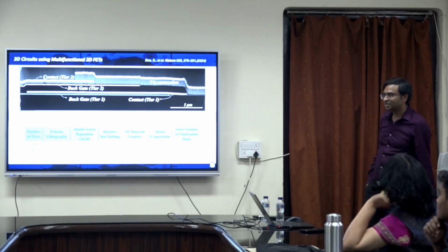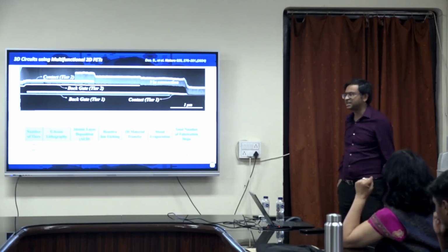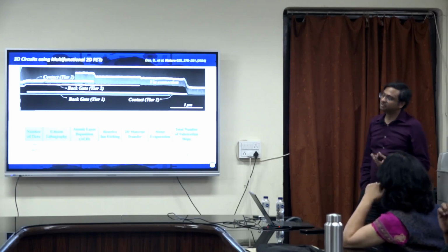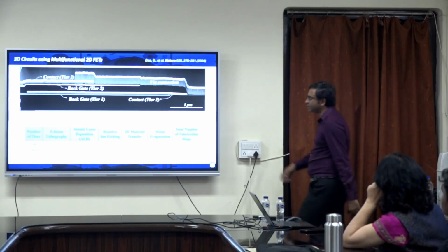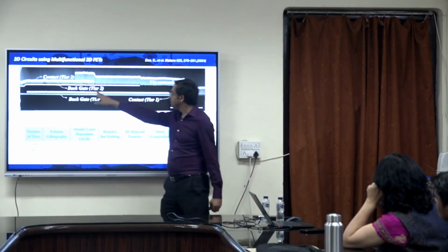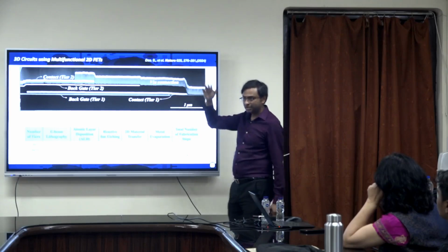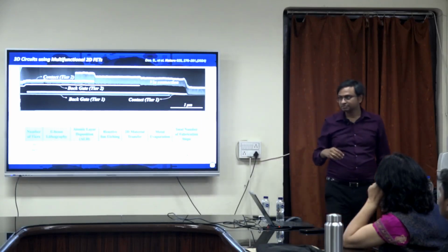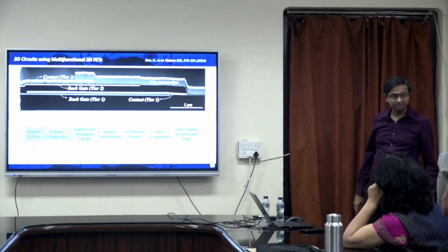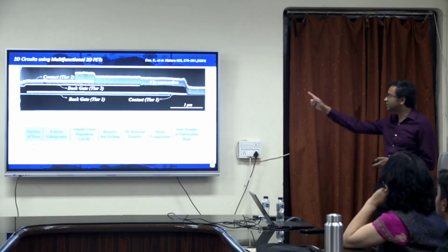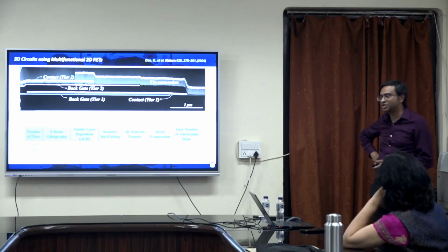Via connections over here I think were titanium. We use titanium. The via is a metal connecting a transistor in tier 1. You see the contact in tier 2 is getting connected to the contact in tier 1, right? Because you are connecting the transistors, literally. So you have to connect the contacts, right? And this is not where we stopped. This is the first 1 crore project.